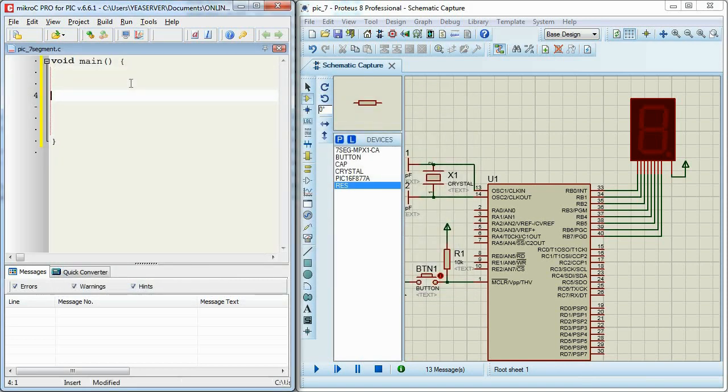First of all, I will put in an infinite loop control structure. I'm going to use while, open bracket and close the bracket. It is good practice to put an infinite loop control structure inside any microprocessor or microcontroller program. Why? Because we don't want the CPU to hang or stop or idle somehow. We want the CPU to execute our program line by line again and again, non-stop.